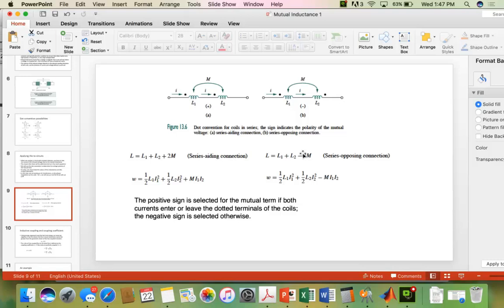Now, if we look at the total stored energy, basically the stored energy in an inductor, as you probably remember from circuits 1, is 1/2 L1 I1 squared. In inductor 2, it's 1/2 L2 I2 squared. In the mutual inductance, the 1/2 term will cancel the 2 here. And so because one of the induced currents is due to I1 and one is due to I2 in a typical problem, then we'll have M I1 I2. Now in this figure, I1 and I2 are equal because everything's in series, but the general form of stored energy is this form right here.